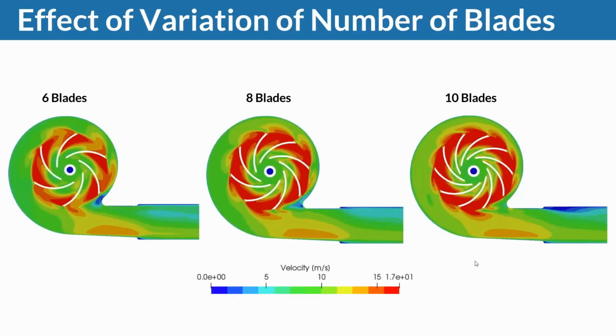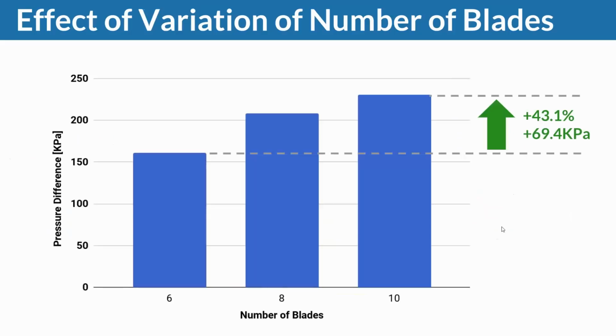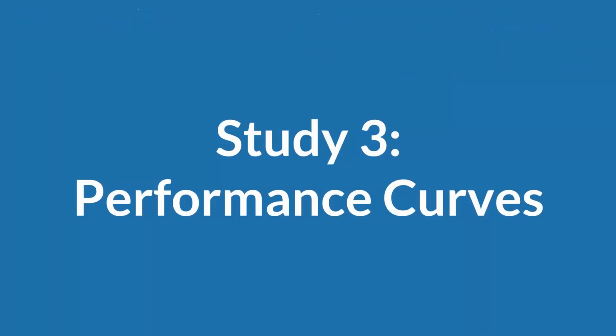The velocity field is also visible here. We could again dig into the trailing edge, leading edge, and go into more detail of this analysis. Putting a number on this, we're going to increase it by north of 40% if we choose 10 blades. Again, quick analysis: 2 hours computing time on 16 cores, so a couple of 100 core hours, manual time not a lot. Quick what-if scenarios like this are possible with SimScale.